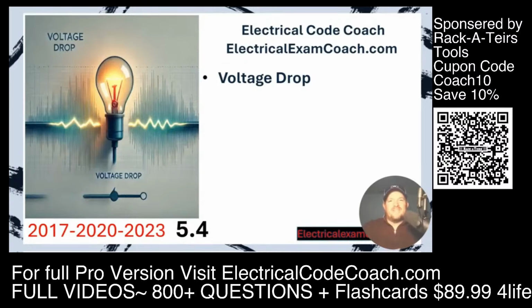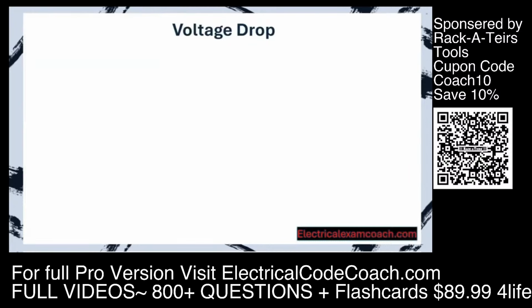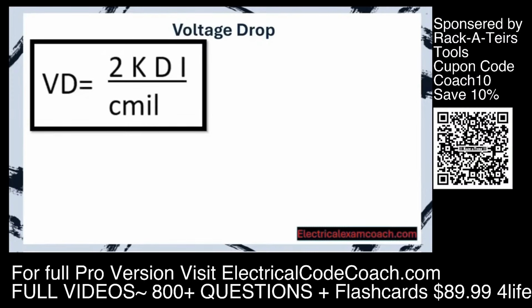Let's get to it. If you were to do an internet search for a voltage drop formula, you would likely find this one right here. Voltage drop equals 2KDI over C mil. And that is an excellent formula. And it's actually the one that I use.